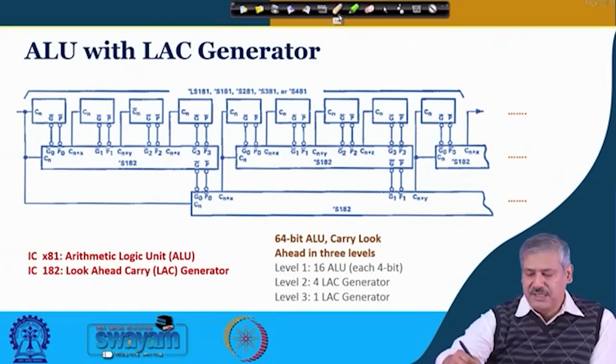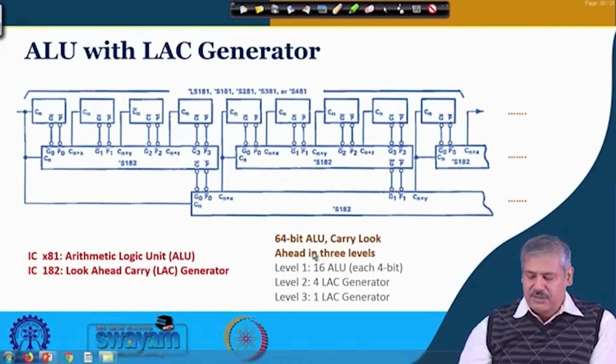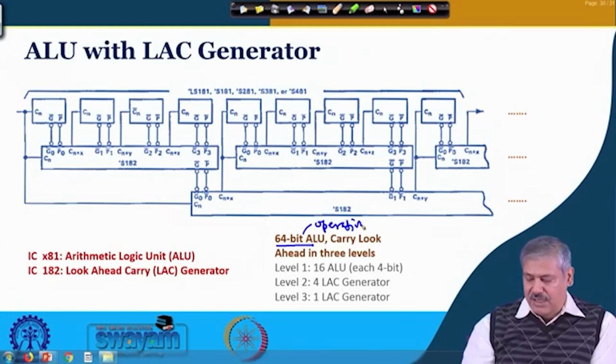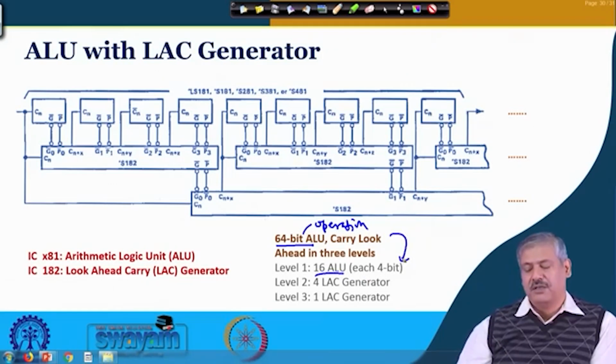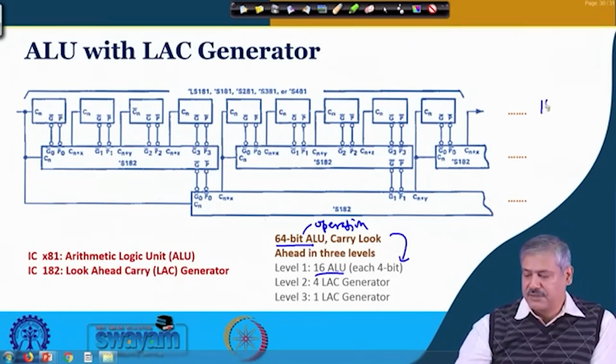So, where you can see the addition where we are using 64-bit addition. For this 64-bit operation we are using 16 ALUs, each 4-bit long, right. So, 74181, so you can see the first level 1, 2, 3, 4, 5, this way 16 such units will be there, okay.